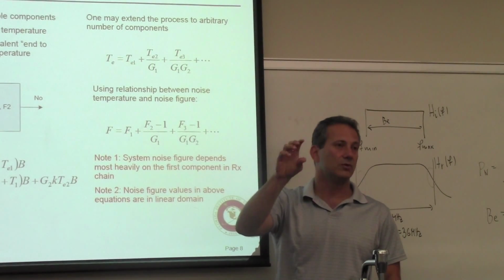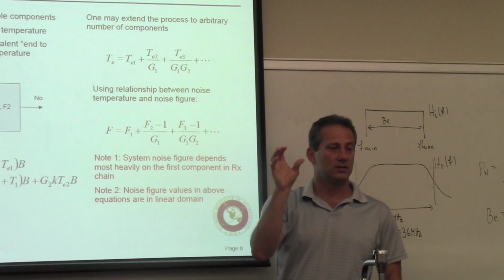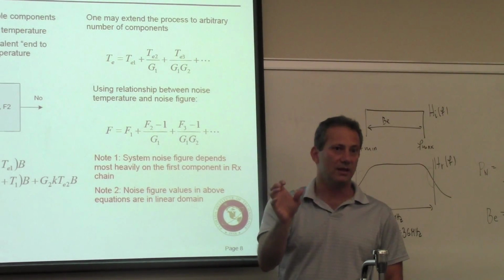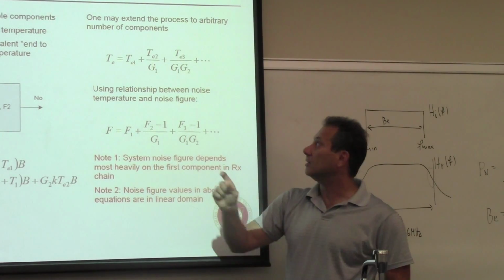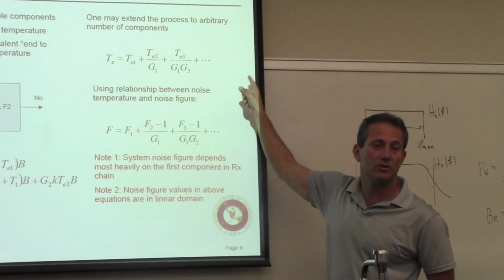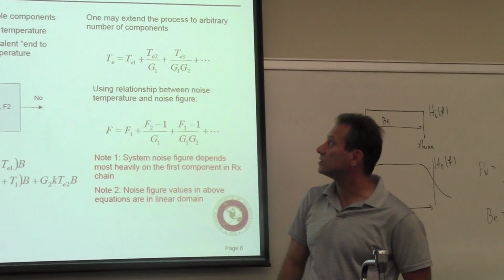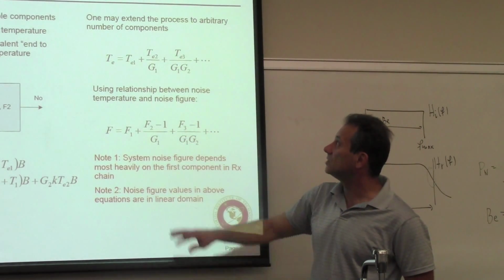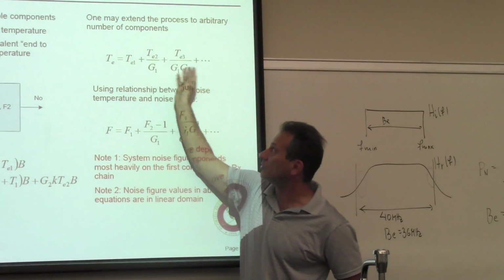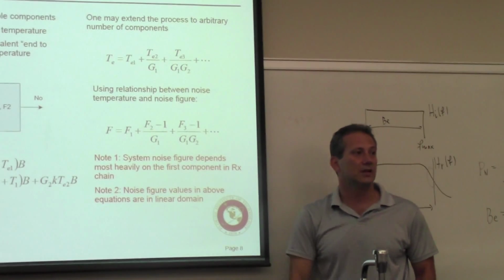There is always what we call an LNA, which is an amplifier that is designed not so much to provide gain, but to provide low noise amplification. And why? Because then the gain of that amplifier figures in all the noise figures and noise temperatures of the devices that come afterwards, and essentially limits the noise figure of the whole system, or noise temperature of the whole system, to whatever is the noise temperature of that element.